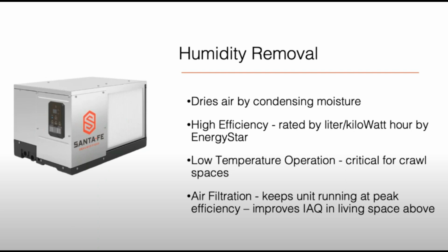It really makes sense to get a high-efficiency dehumidifier with low-temperature operation because this is critical for crawl space. There's a big difference between a dehumidifier you can pick up at Home Depot and a commercial-grade crawl space dehumidifier. The commercial-grade dehumidifiers are designed for low-temperature operation. The point is, those dehumidifiers not designed for crawl spaces lose capacity quickly once they get below 65 degrees, which is the average temperature in a crawl space.